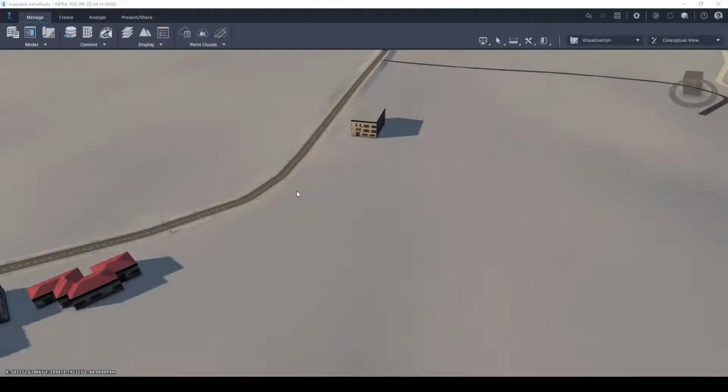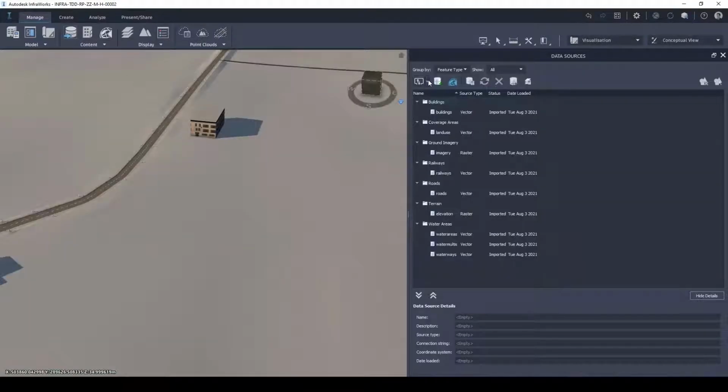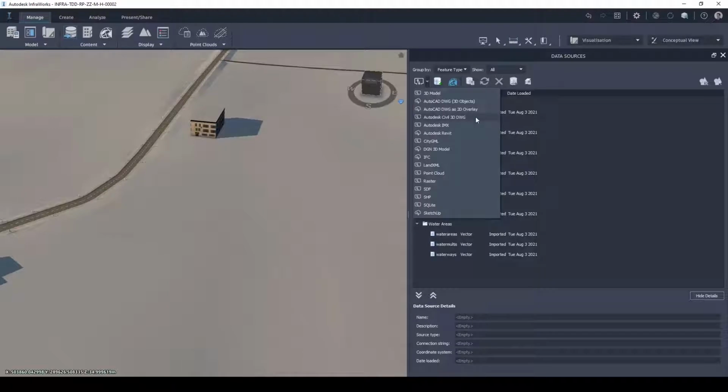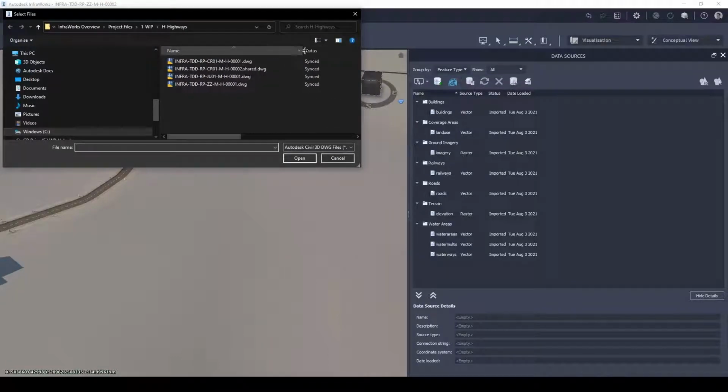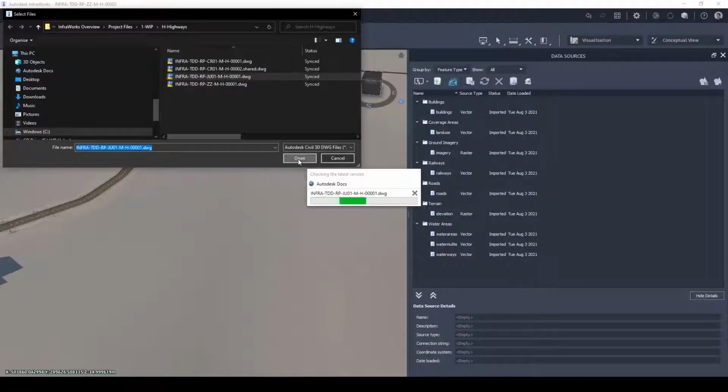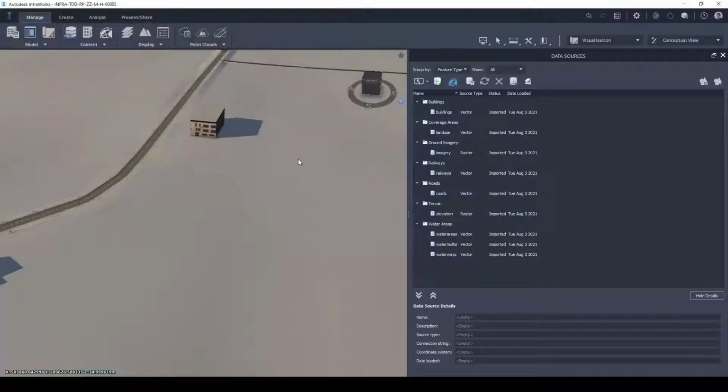Back inside of Infoworks, we have the ability to import Civil 3D surface data into the model once further project work has taken place. This could be surface data taken from an updated survey, giving more accurate elevations on a further refined grid, an exported surface from a linear corridor, such as a road, railway or earth embankment, or it could simply be a proposed tin surface created inside of Civil 3D, using points, feature lines, and so on.